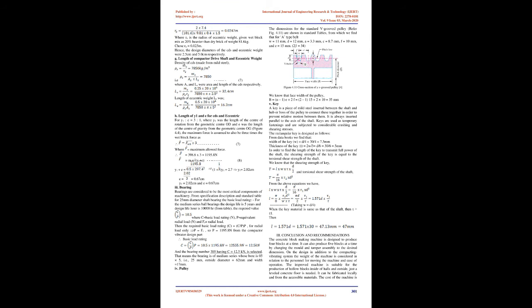E. Operating stress, S. This is given in the equation. F. Diameter of the eccentric weight and compactor drive shaft, CDs. The CDs carried the weight of the wet block mix in bending under minimum tension with a combined shock and fatigue factor of 1.54. The drive torque, T, was given in the equation, for the motor which ran at 2840 rpm and P equals 2.2 kilowatts.